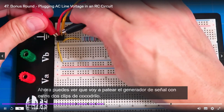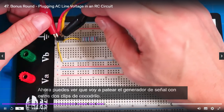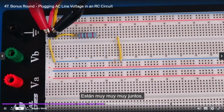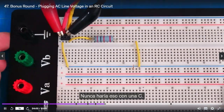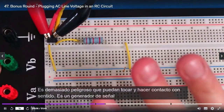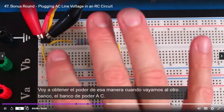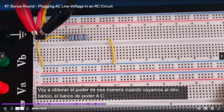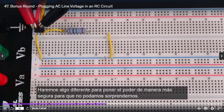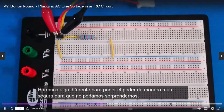Now, you can see I'm going to connect the signal generator with these two alligator clips. They are very, very close together. I would never do that with AC. It's too dangerous. They could touch and make contact, but since it's a signal generator with very low current, I'm going to get the power in that way. When we go to the other bench, the AC power bench, we're going to do something different to put the power in more safely so we can't shock ourselves.